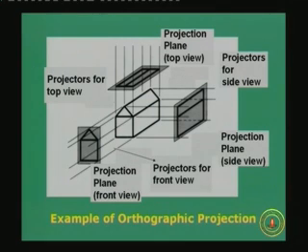Okay. This is an example of an orthographic projection which shows the three types of views which you can generate for an object, correct. I was talking of a top view, a side view and a front view. So, here you see typically a structure which looks like a house with a tapered roof. You can visualize that I have put a rectangle at the bottom and then of course a tapered prism type of a structure on the top.